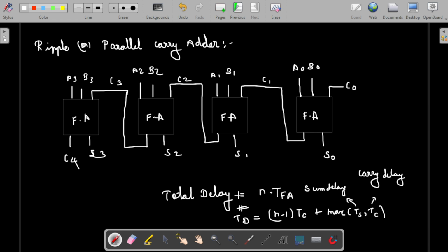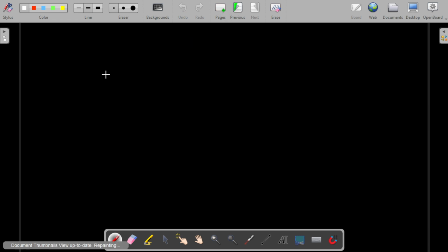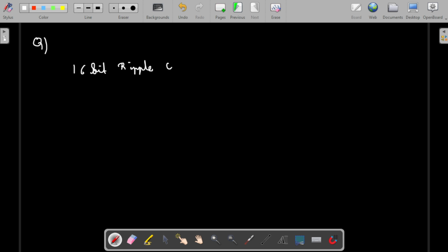I am giving you a question, please make a note of it. The question is: we are using a 16-bit ripple carry adder. The carry delay TC is 12 nanoseconds and the sum delay is 15 nanoseconds. What will be the total delay TD? Please pause the video and try to answer it.